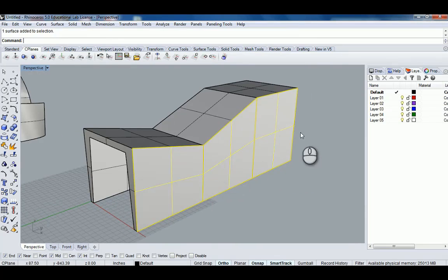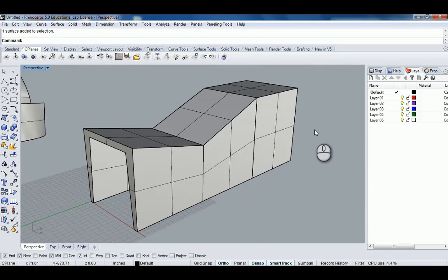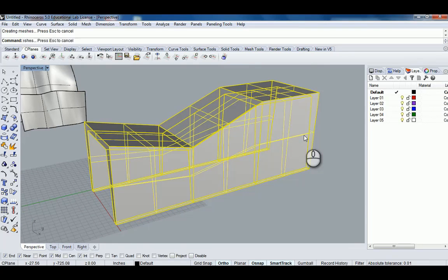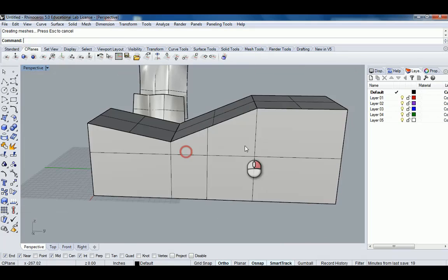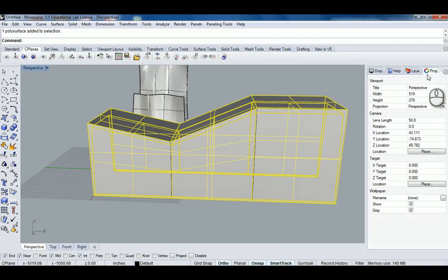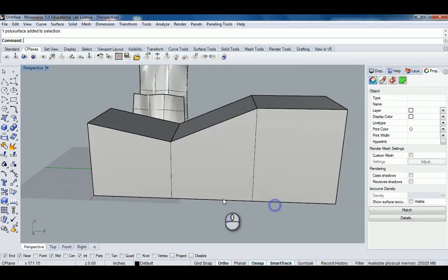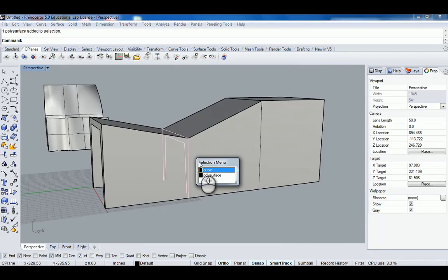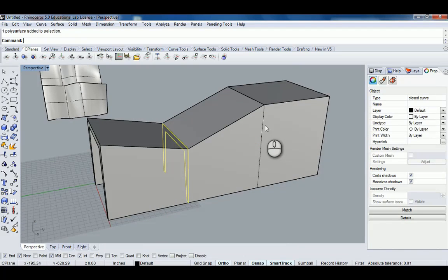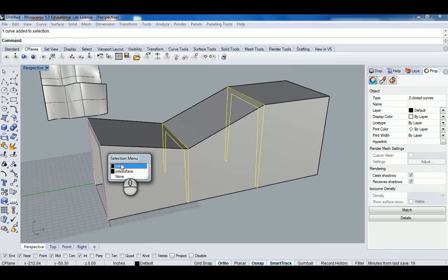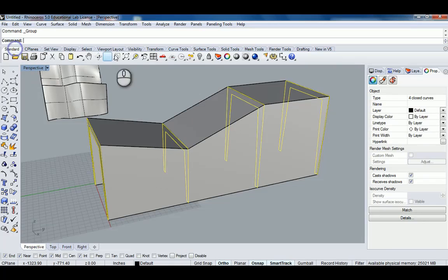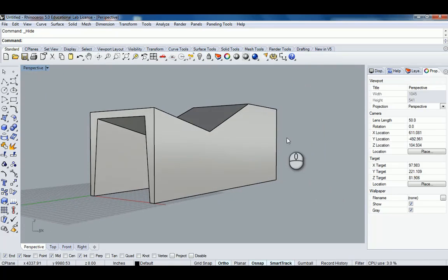And the way that we would do that is, let me unexplode this real quick. We can merge all faces. And then basically what that's done is, let me turn our ISO curves off too. So now you can see it's just a cleaner shape. Hopefully that speaks a little bit to what your question was. You can still simplify the surface after it's been made. If I hide these cross sections, I'm going to group them and hide them. So now that's 1 surface versus the 3 that it was before.